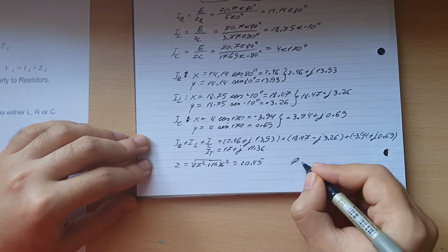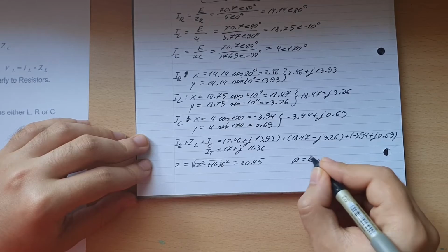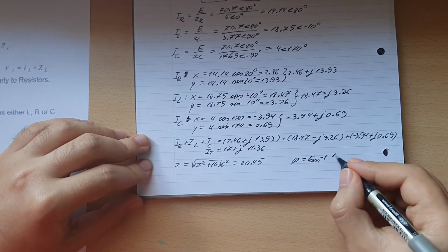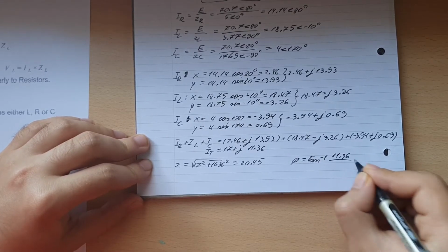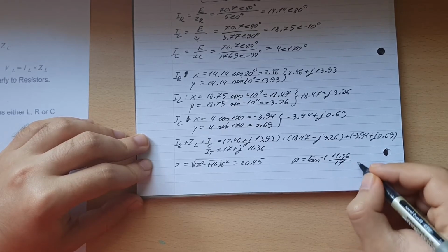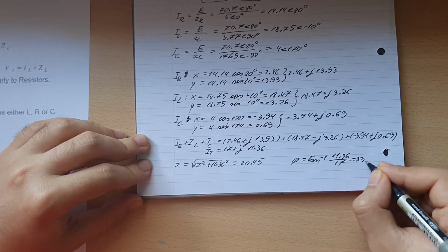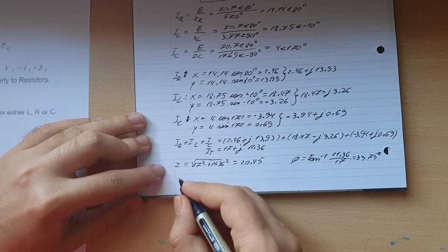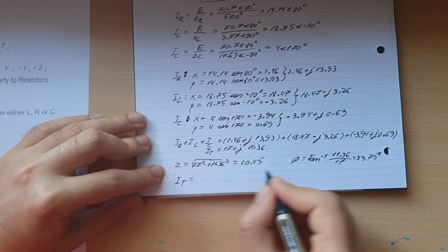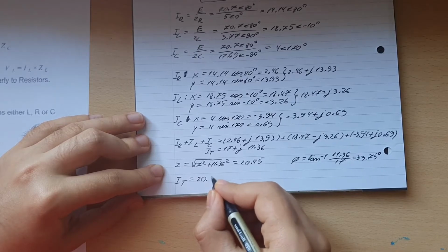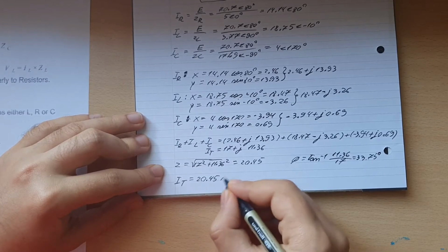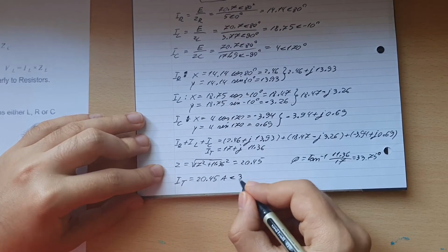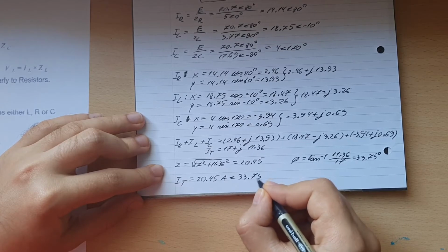Then the angle is equal to tan minus 1 of 11.36 divided by 17. That one is equal to 33.75 degrees. Alright, so then IT will be equal with those two values, so 20.45 amps at an angle of 33.75,